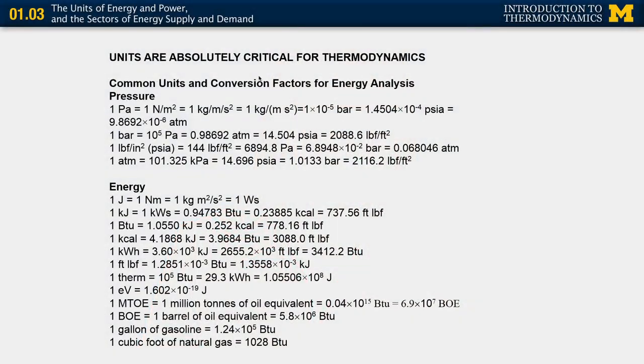Okay, units are absolutely critical for thermodynamics. They're actually very helpful to us, and sometimes they can be hard in terms of our understanding and being flexible. Common units and conversion factors for energy analysis are provided on this slide and the next slide. We're going to start with a discussion of pressure, which has a lot of different units that are commonly used. In SI units, Pascal is the appropriate measure for pressure, but we'll often see bar or atmosphere, which are also very common in this community, or PSI.